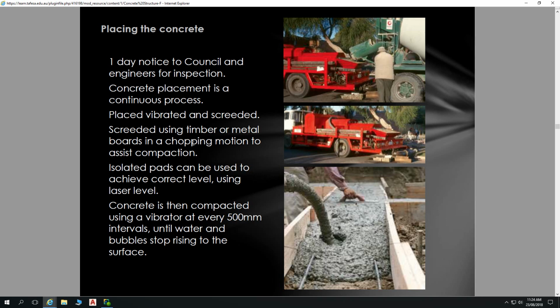But they could do that because they'd started that job hours ago, pouring that section right at the end, and working their way through. They're troweling off that section while they're still pouring this other bit. That happens in major jobs. Typically with residential work, it all happens in one go. It's not chaos, but it's a lot of activity right at the start.